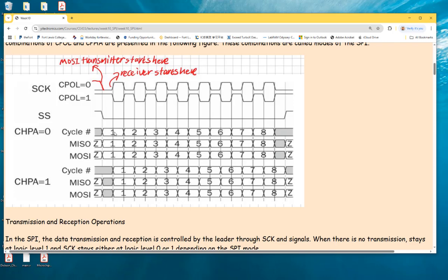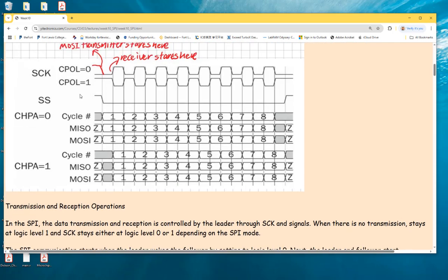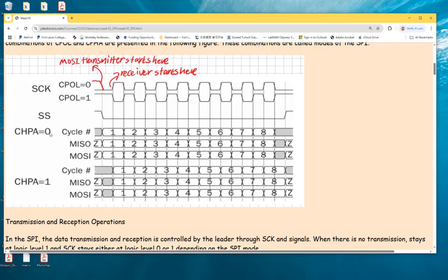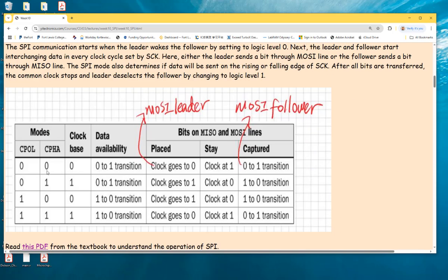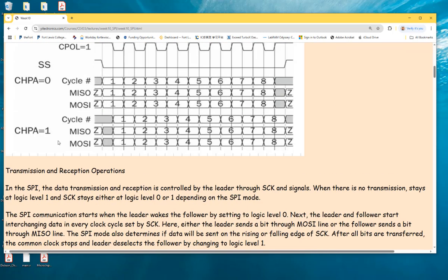And the phase here, again the typo, CPHA, defines the phase when the data is being taken into the register of the receiver. Okay, so basically the data, you can see every time it's being taken in, it has to be in the middle. So the edge has to happen in the middle of the data, so it's getting the most reliable data sample, right? So for example, if we choose 0, 0, you can see there's a table. It's a bit confusing. I don't really like the table a lot. So, but let's come back and look at this one.